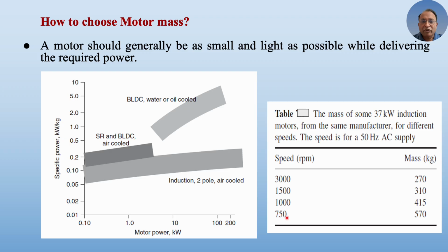So that is why we observe that the motors which are used in EV application have to operate at a very high speed. Then only will they be lighter in weight. For the same rating motor, if we prefer a lower speed operation or a lower speed rating, then the weight of the motor will be large, and consequently this will not be preferred in case of EV application.